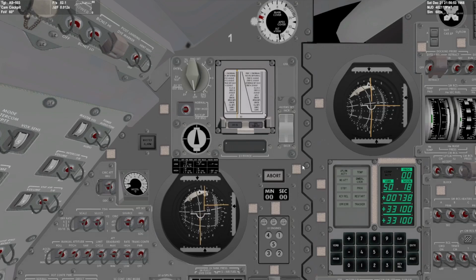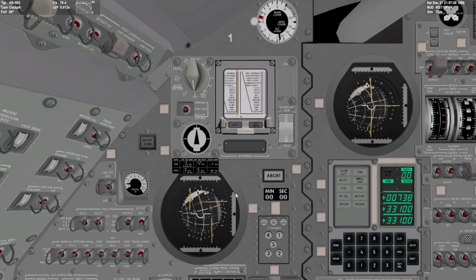So since that is the next thing in the checklist, and you can see this arrow needle is actually going too high up, so it's not going to stop until it hits the edge of that deadband, because again, the deadband is wide, so the computer just lets it go. It's a little more loose with when it actually stops the maneuver here. So we can see it's still going here, but it will come to a stop shortly. And once the attitude comes back to the deadband, it'll kick it in the other direction.